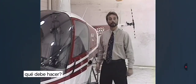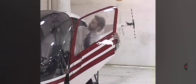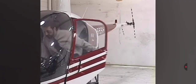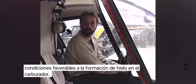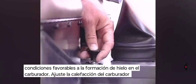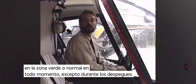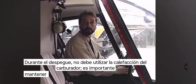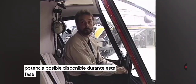So what should you do? Use the carb heat. When operating the helicopter in conditions that are favorable to carburetor icing, adjust the carb heat to keep the carburetor air temperature gauge in the green or normal range at all times, except for takeoffs. During takeoff, the carb heat should not be used. You'll want to keep as much power available as possible during this critical phase of flight.